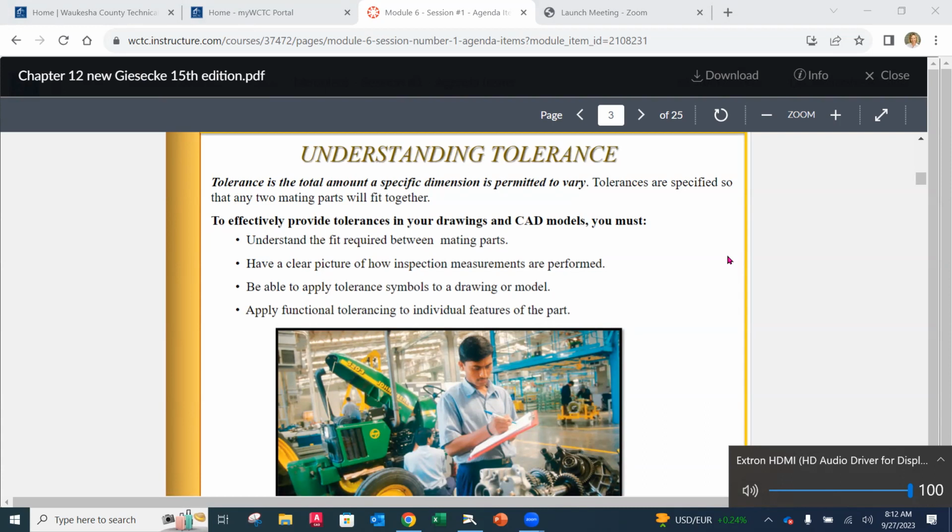And what that means is, in the drawing itself, there are a number of dimensions that we've put on drawings already that have no tolerance specifically behind them, but every dimension on a drawing has a tolerance. And if it's not there, like Josh said, then it defaults to the title block. So every dimension on a drawing has a tolerance, whether you intend it or not.